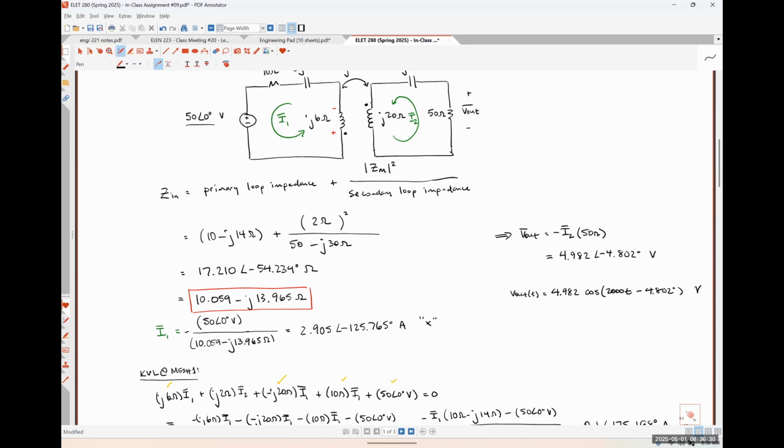So if there's a defined current or something like that, it winds up flipping directions. The voltages flip polarities, etc. But everything has to be flipped over. But you can literally think of it as physically just twisting that part of the circuit upside down. So just as a heads up, sometimes that is an easier way to look at things when it's complicated and you have two separate individual magnetically coupled systems like we do in a transformer.